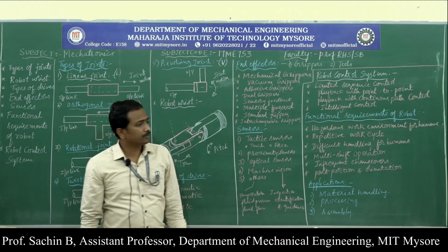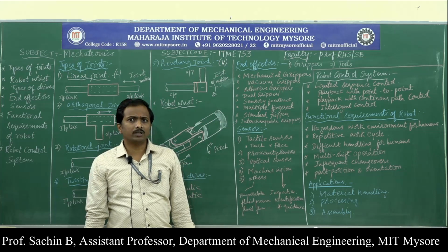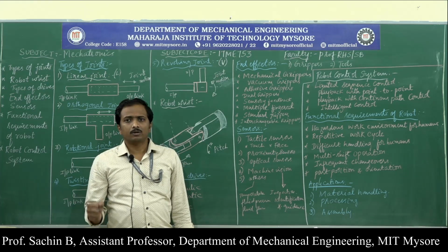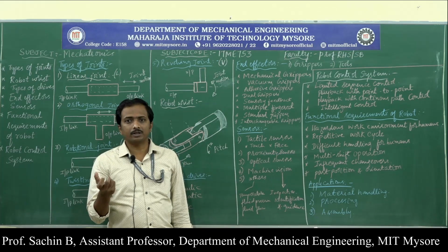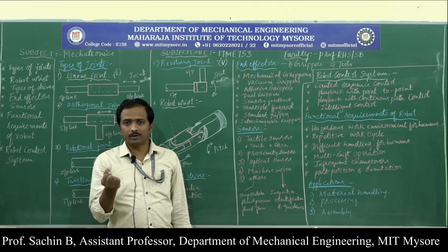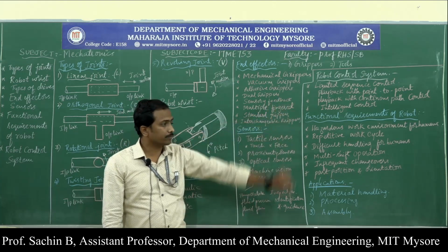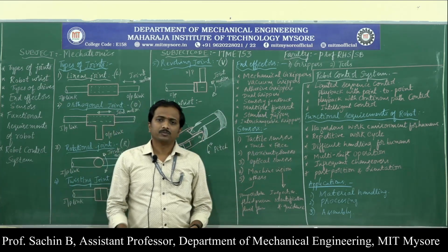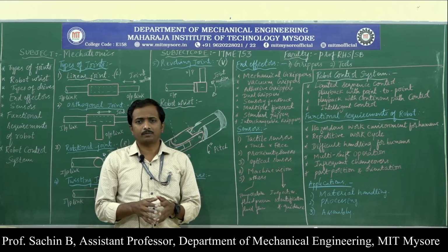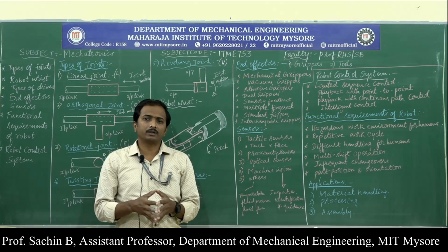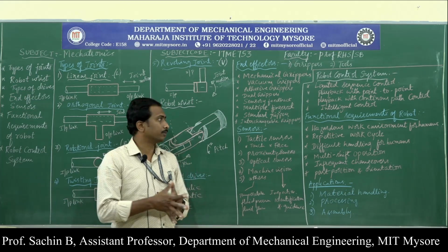The adhesive types of grippers are mainly used for holding objects that are very difficult to hold in many industrial applications. If the surface finish is high for many components, after grinding or turning operations, it is very difficult to hold them. We can go with the help of adhesive grippers. Again, dual grippers are grippers where replacement of the grippers is possible. They are used for working on multiple different tasks, and multiple tasks can be easily performed with the help of dual grippers.